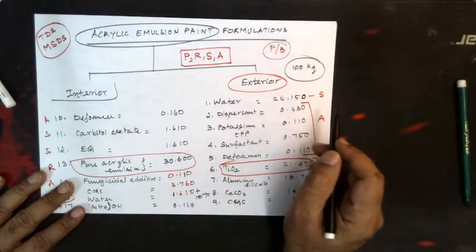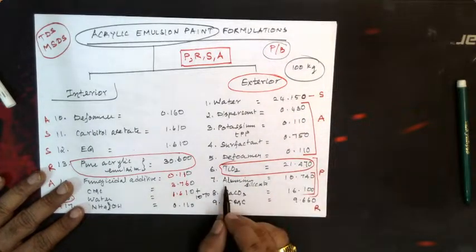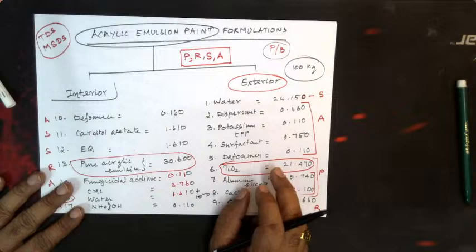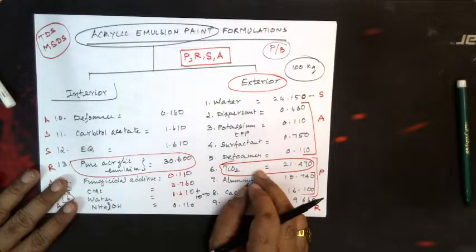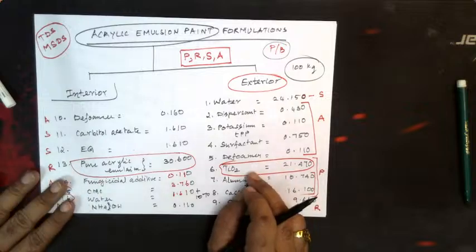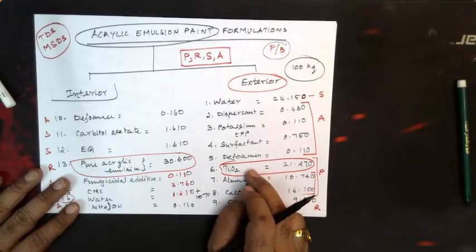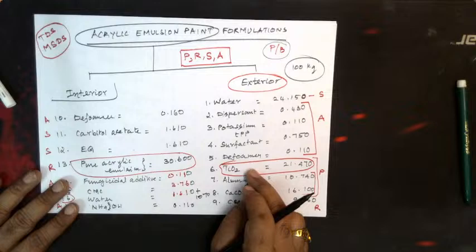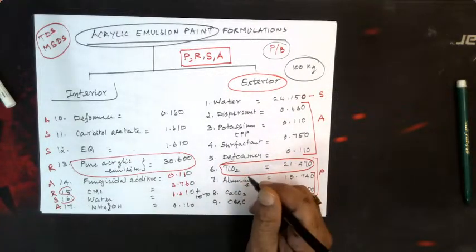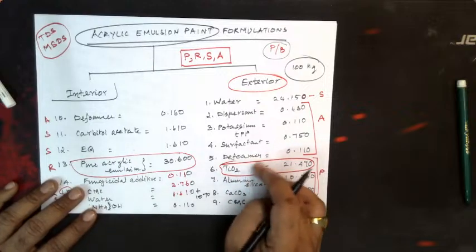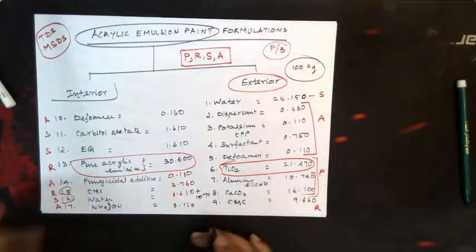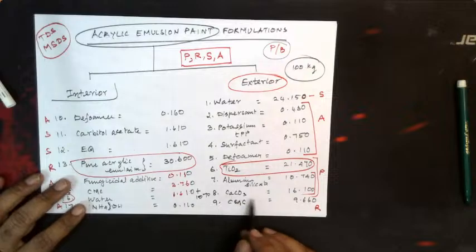Now, we have discussed this titanium dioxide. That is for aqueous based, that is water based paint. Anatase is better used, but there are some disadvantages of anatase. It has a yellowing tendency, because when it is exposed to UV light, it yellows and gets deteriorated, and it has less hiding power, opacity also. So that is why some people use a combination of rutile and anatase. Okay, right. And calcite, calcium carbonate, that I have discussed.